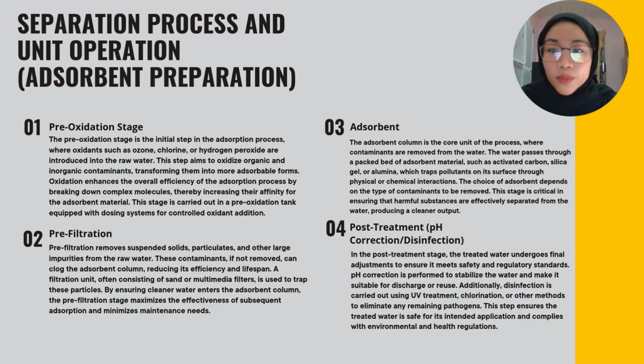The next one, we have pre-filtration. Pre-filtration is in order to remove the suspended solids, particulates, and other large impurities from the raw water. These contaminants, if not removed, can clog the adsorbent column, reducing its efficiency and its lifespan.